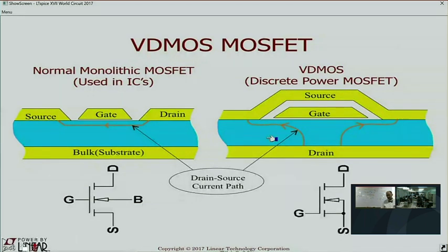Now, for power MOSFETs, the answer is you don't import it. You use a MOSFET model that's in LTSpice, because LTSpice has a native circuit element that actually behaves like a power MOSFET. SPICE programs don't have that. SPICE programs were for IC design, which are lateral devices, because you can lithograph them onto an integrated circuit. But a power MOSFET is a vertical device, and as a vertical device, you can't print it on an integrated circuit, and it has entirely different Miller capacitance behavior. You cannot use the device equations for a lateral MOSFET.